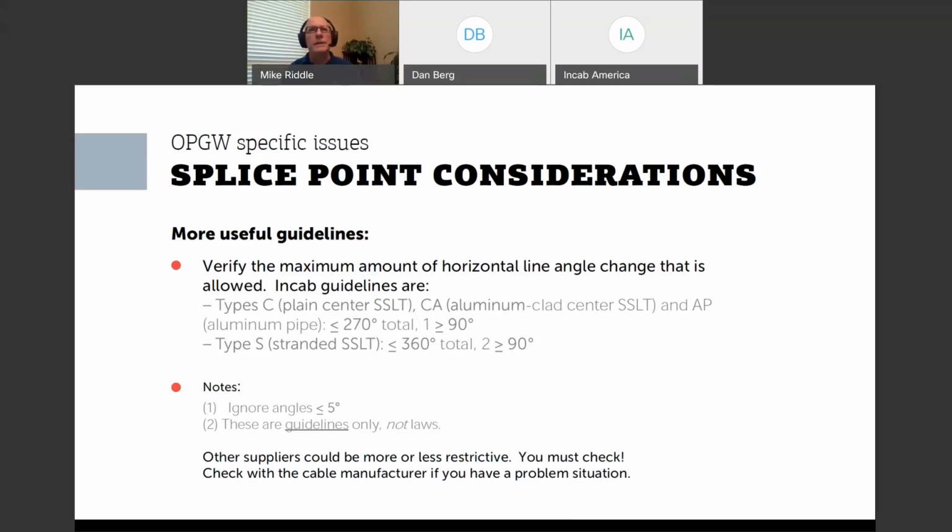Sometimes it can exceed that, but that's what you try to maintain. And then you allow the cable to go no more than 60%. So the two, sometimes they're similar with a stranded stainless steel loose tube cable, but for center tube cables, the maximum rated design tension is above the zero fiber strain margin, and also that's true for aluminum pipe type cables as well. Sorry, rambling answer there, but I hope I answered your question.